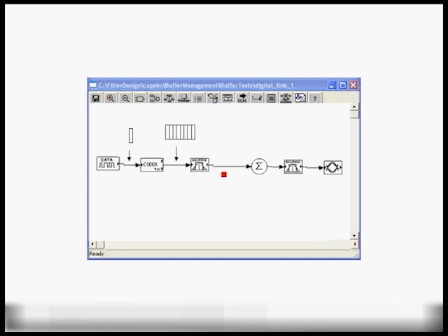So the simulation is very efficient. You have one call to this block, and this block will consume all its input samples and output them before returning back to the kernel, so it's very efficient. And as we said, we have a bounded memory footprint, even though you can simulate, for example, a gigabit worth of information.